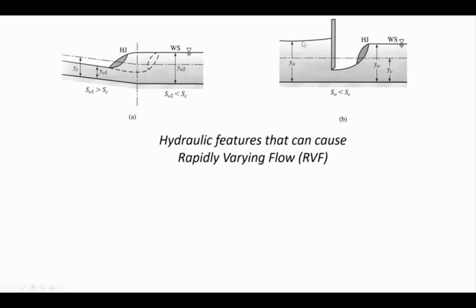And so what happens is you'll notice it's getting a little bit deeper as it approaches that gate. Here it was the normal depth, but it's not the normal depth the closer you get to the gate, because the water pools a little bit in order to gather energy to flow under the gate. And at this location, the conditions are supercritical. Even though the slope, as this is showing, is a mild slope, as it's called. It's a slope that wouldn't ordinarily cause supercritical conditions. It's a slope that can't support supercritical flow for very long.